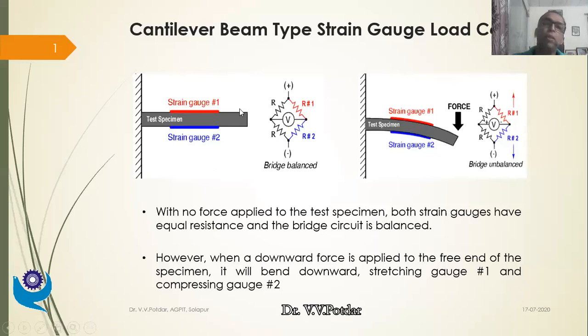Now what kind of load is this, what kind of force is it? It's called a bending load. Now when the beam is subjected to bending load, if you recollect what we have studied in strength of materials, the beam will have one neutral axis. So at the neutral axis there will not be any stresses or strains. Above the neutral axis and below the neutral axis we see the more intensity of stresses and strains.